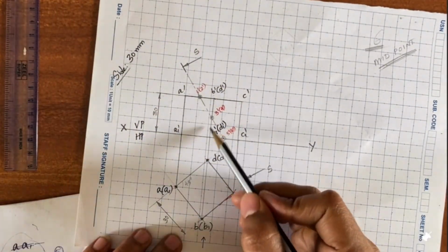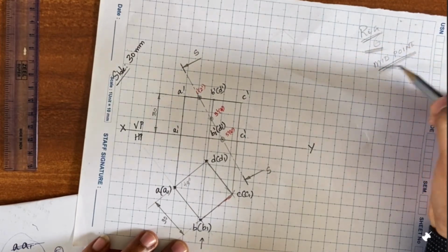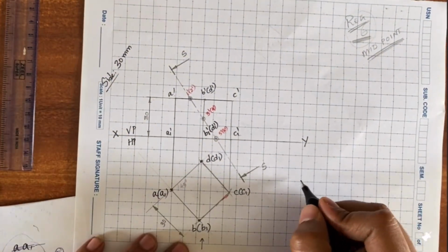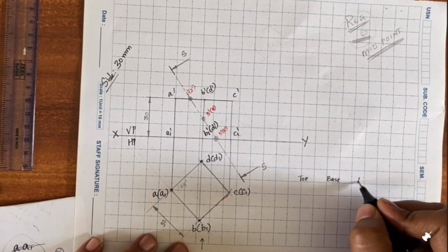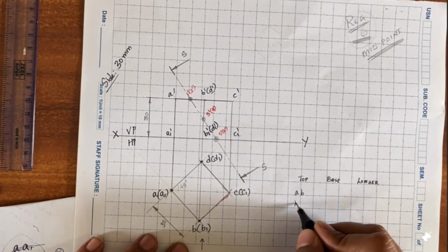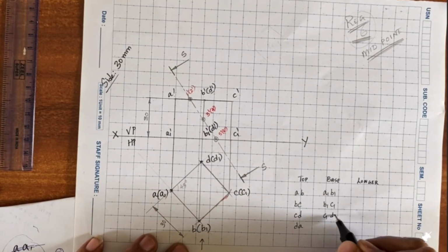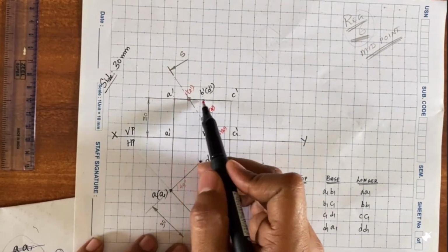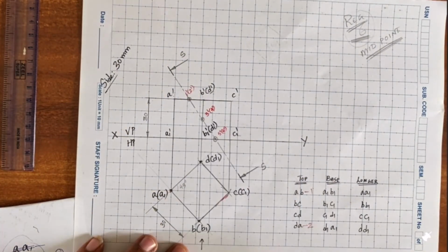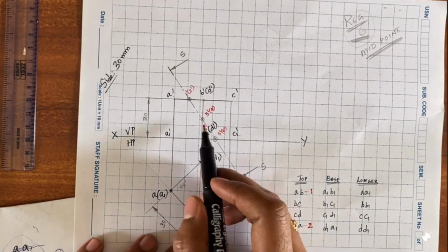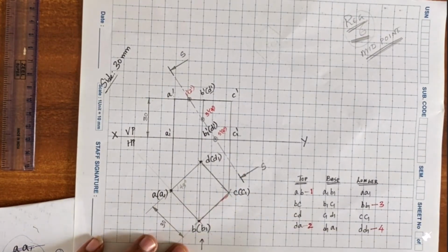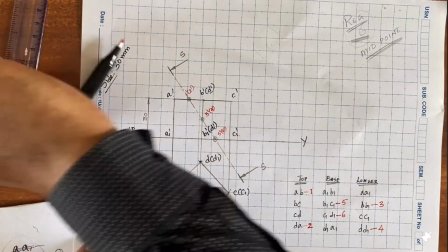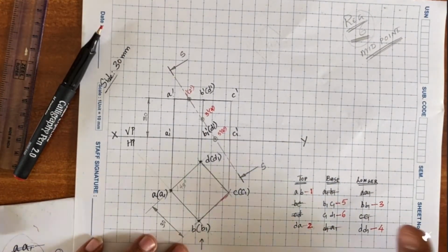Now since we need a regular hexagon of 6 equal sides, we will find out 6 midpoints as we have done here. Let us see where these cut points have appeared in the cube. The 6 edges we will identify by listing out all the edges that are present in a cube: the base edges, top edges, and the longer edges. Check each edge and note down if the cutting plane is intersecting the edge. If it does, whatever point that we have marked in the sectional plane, we'll highlight that point in this list of edges. Once it's done, the remaining edges have no cut points.